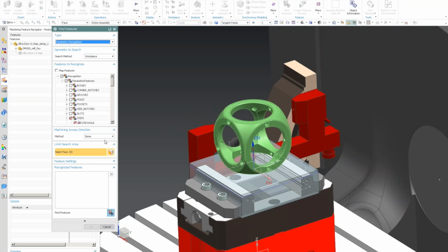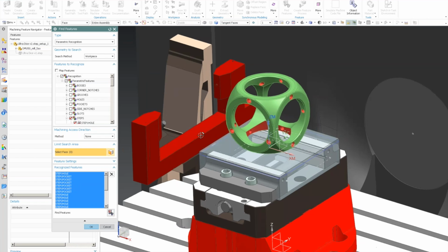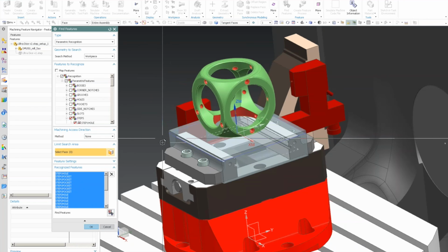What we really like about this, especially when it comes to deep cavity molds or areas where you have holes that you might have a collision, is that it automatically does collision avoidance. It's picking up the tool axis for you. You don't have to create separate CSYS objects to program the holes. So if they're all at different tool axes, it really saves a lot of time.